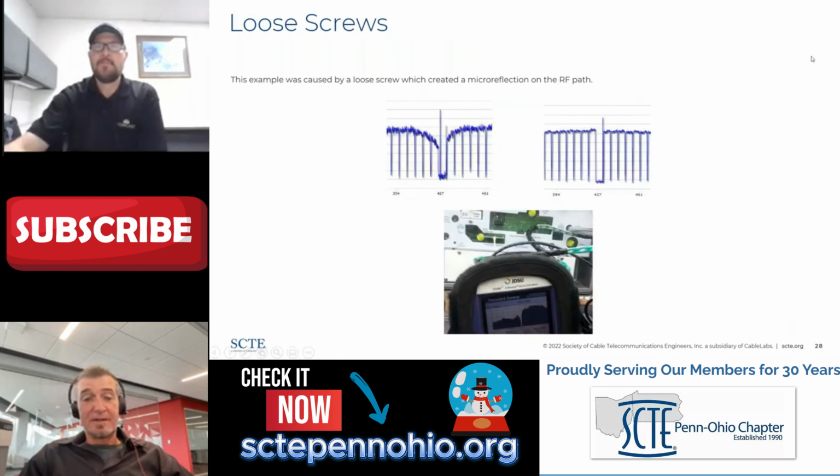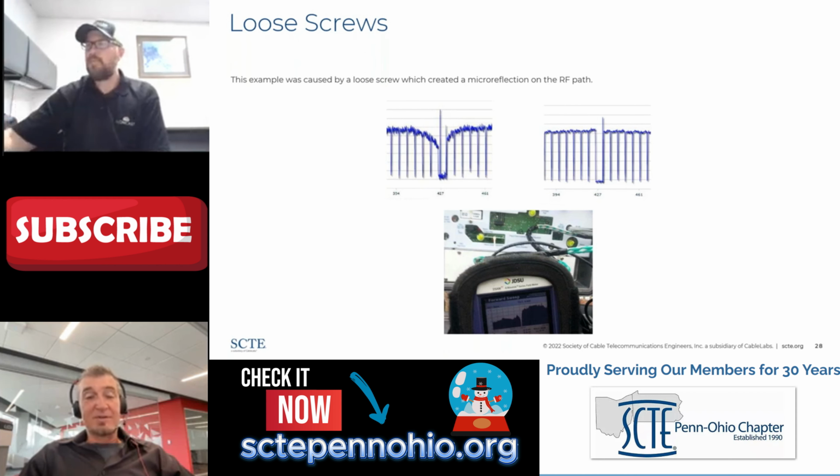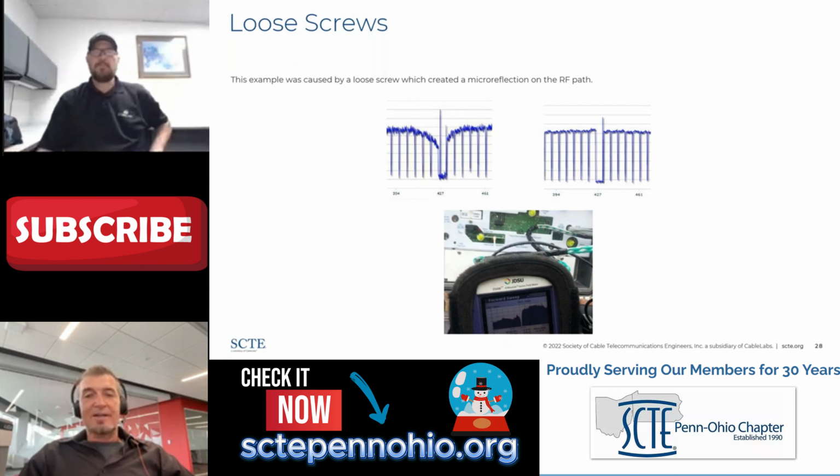This is a good example. Like I said, I remember this was Jason Chapman at the time. The important thing to notice about this suckout, this was just a loose screw, and notice that the center frequency of the suckout is right on that pilot, that AGC pilot.